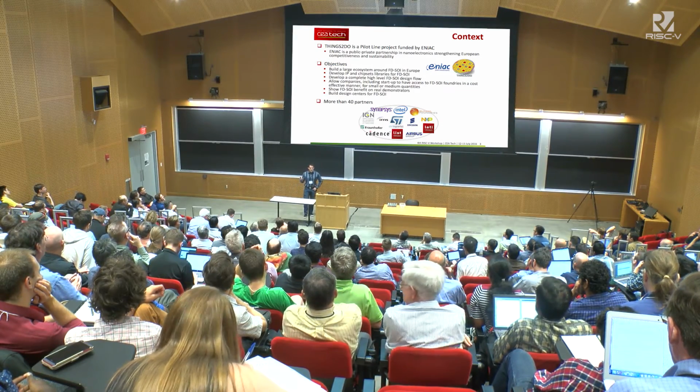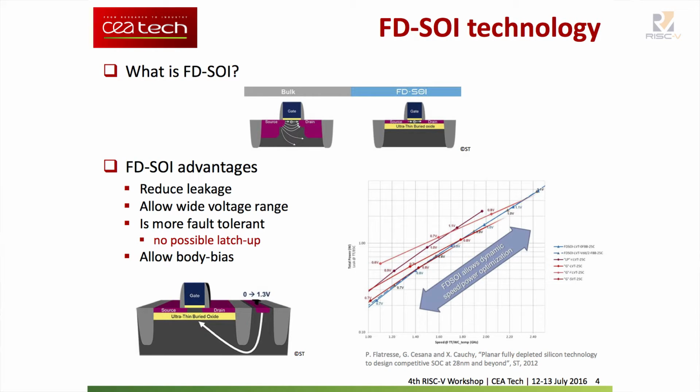So, what is FD-SOI? I don't know if you know this silicon technology. When you want to build some transistors, on the left, you have a bulk technology for CMOS with source, drain, and the gate. And in fact, it has a lot of leakage.